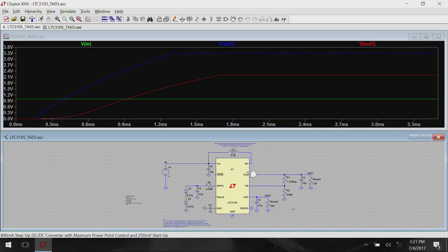You do not want power flow to happen this way and reduce the power output here. So, you want to put this into a complete shutdown state such that the output remains whatever it is. You do not want the LTC to draw power in the reverse direction and bring down the output voltage. This is essentially what under voltage lockout is. The converter chip has to do a complete shutdown, as I have written here, in order to ensure that the chip is indeed stable.